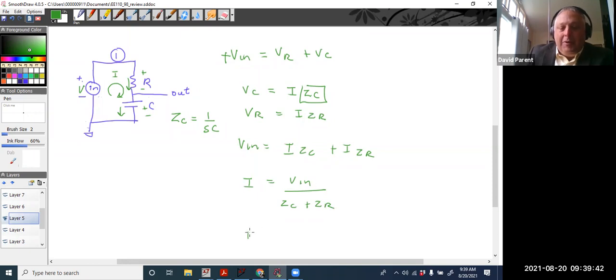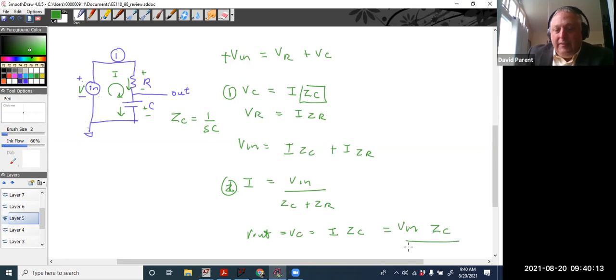And then V out equals VC equals I ZC. I'll call that equation 1, we'll call that equation 2, and we substitute, and we get V out equals V in times ZC over ZR plus ZC. Okay.